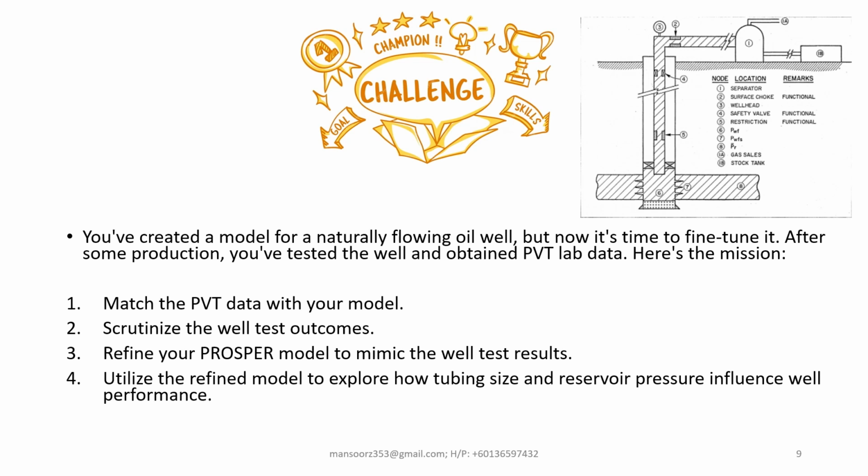First of all, you need to match the PVT data with your model. That's why the accuracy of the PVT is crucial in modeling the well. Then we're going to scrutinize the well test outcomes and refine our Prosper model to mimic the well test results, and finally utilize the refined model to explore how changes of certain variables, for example here tubing size and reservoir pressure, will influence the well performance.